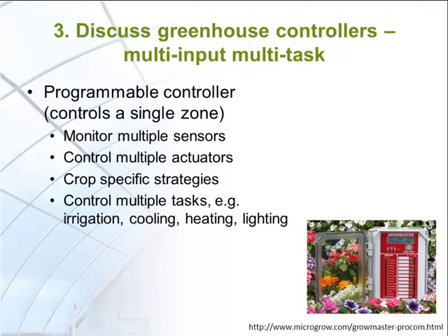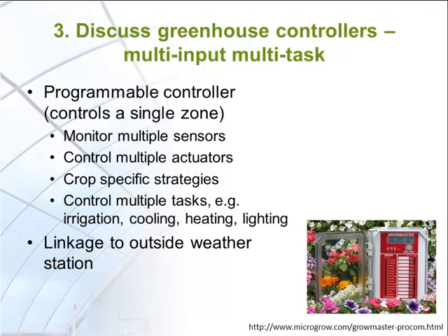Further, this type of system has the ability of using weather station information such as outdoor temperature for the vent opening angle control, and outdoor wind speed information from the weather station can also be used to protect the greenhouse structure by closing vents under high wind conditions. Data recording ability is another valuable feature of this type of system.